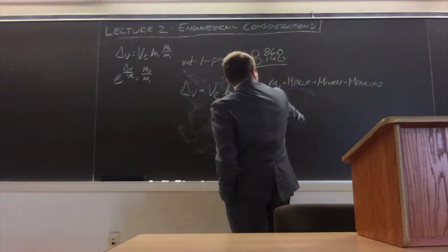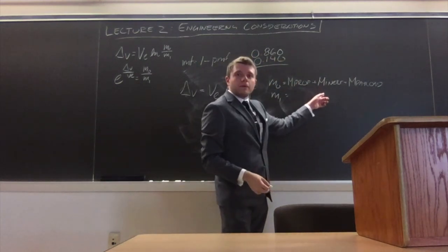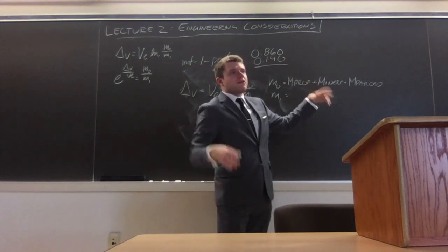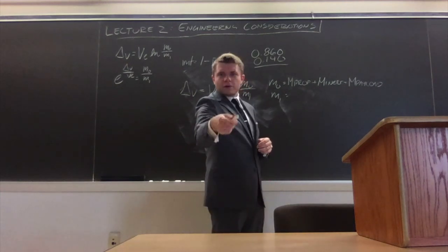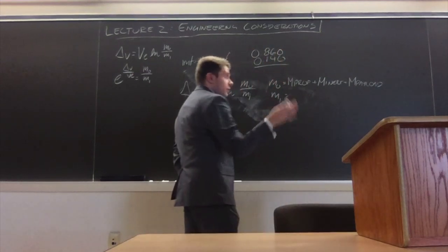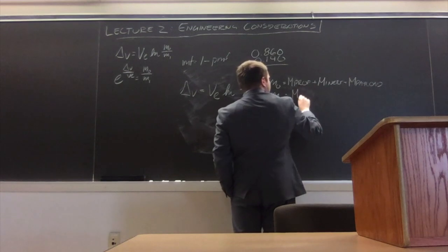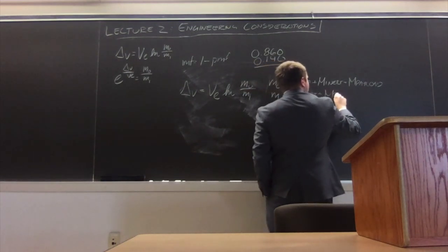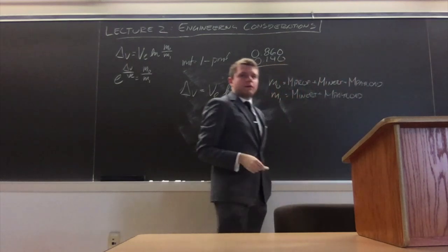And then m sub 1 is everything that's not burned. And we're going to actually lump the inert mass in with propellant residuals and such. We're going to consider that as part of the inert mass. It's something that does not directly contribute to propulsion. And of course, the final total mass is just the inert mass plus the mass of the payload. So that is our general setup.